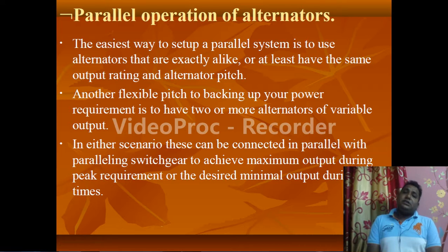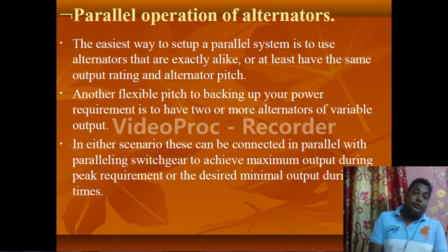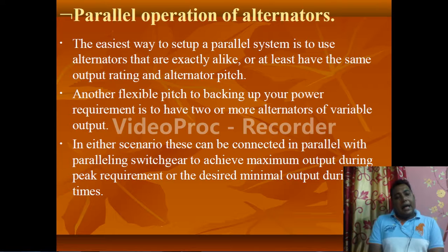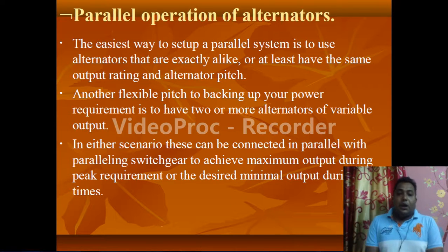Another flexible way of backing up your power requirement is to have two or more alternators of variable output. Very important point. In either scenario, they can be connected in parallel with paralleling switch gear to achieve maximum output during peak requirement, or the desired minimal output during other times. So when we are paralleling all the alternators together, we can think of that over 24 hours of a day.